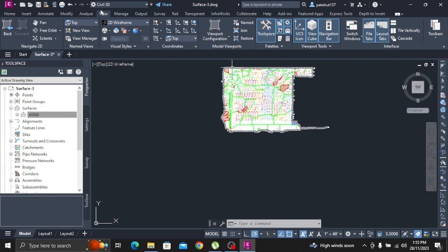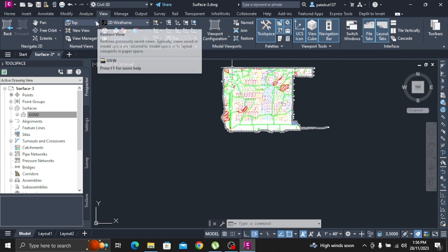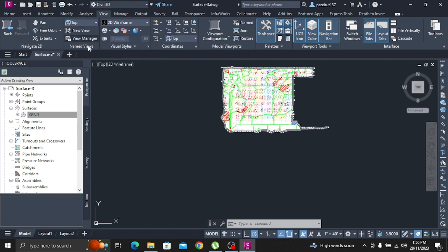In the drawing window, click the line on which the surface labels were drawn. Grips appear on the line. Select the grip in the circle at the upper left. It turns red, indicating that it is active. Drag the grip to a new location and click. Notice that the labels update automatically to reflect their new position.